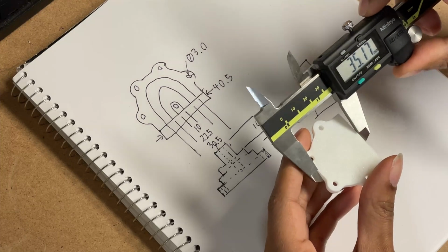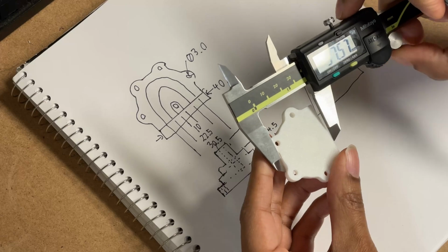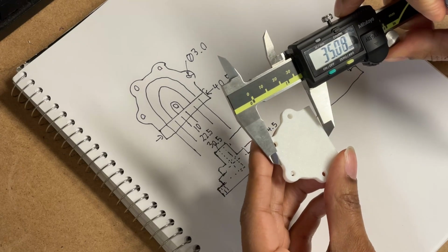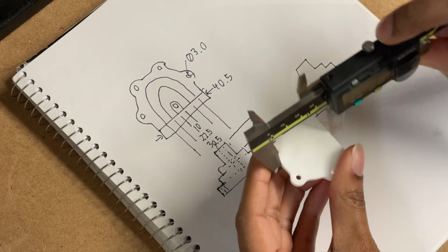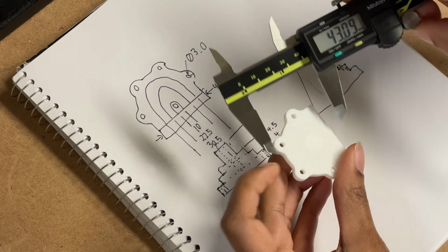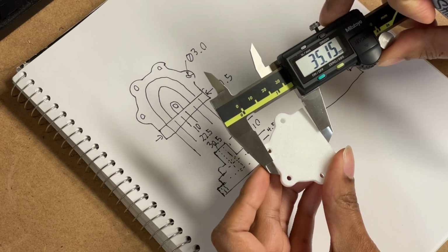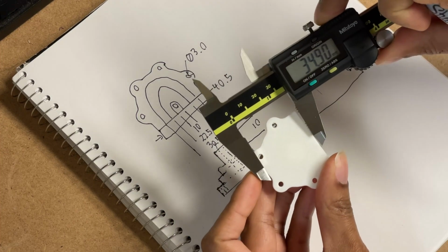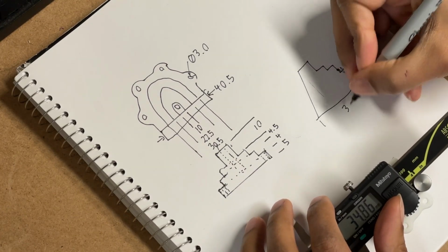Let's see, what if we measure this? Now you'll notice I'm holding the caliper, and this is a pretty awkward measure, but I'm holding it flat, as opposed to like this, because then it's hard to know if I'm getting it straight on. But if I hold like this, I can get tangent on this one side, and then I can ensure that it's flat with the jaws on the other. I'll call that 35 from here to here.